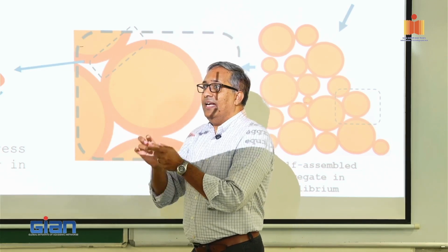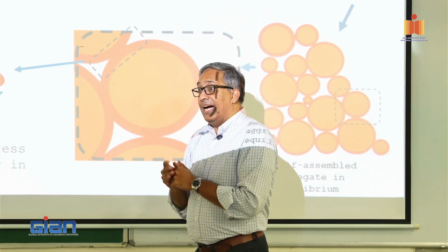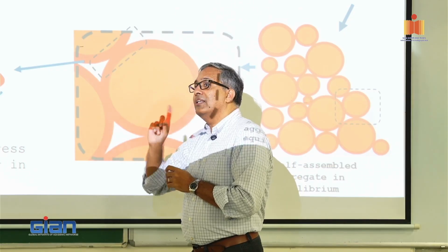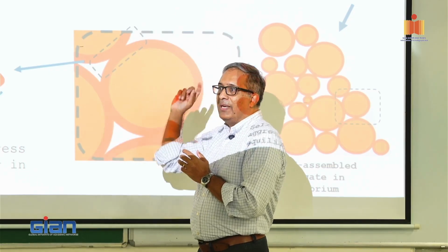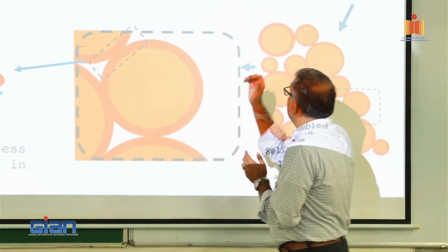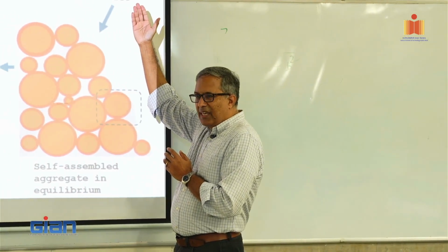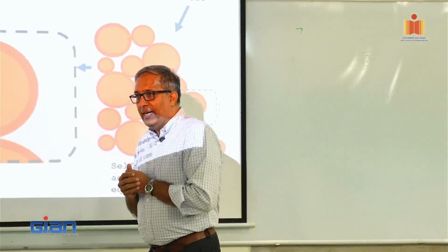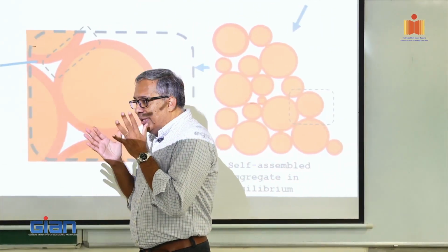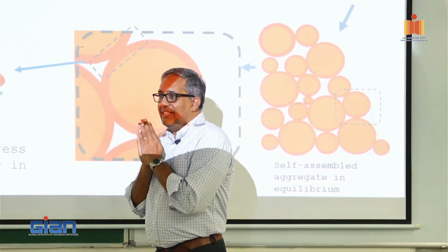So if I increase the yield stress of the paste, I expect a smaller slump value. It will not slump as much. Then I should be able to keep higher level differences in concrete. It starts behaving more like a solid. Why? Because the stress required to induce flow in cement paste is very high.